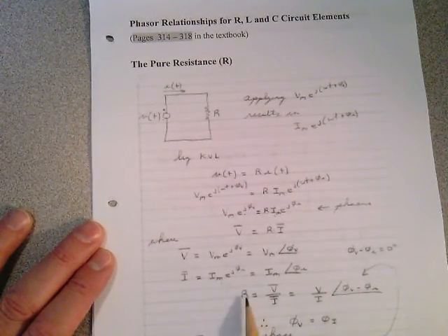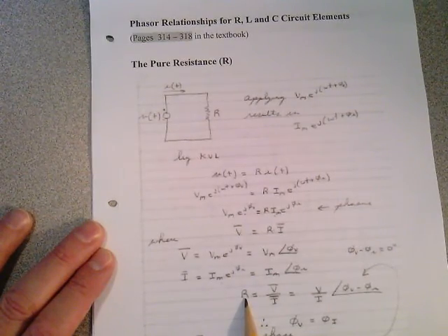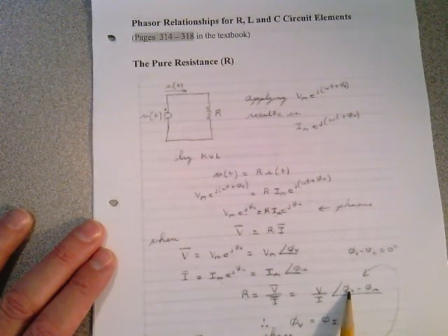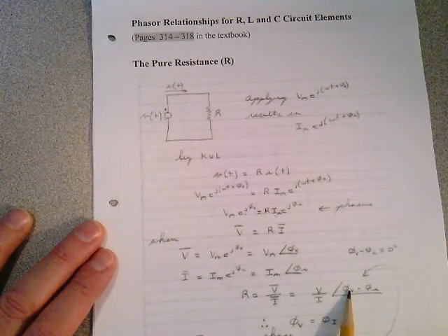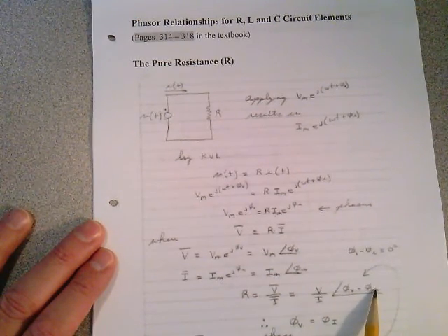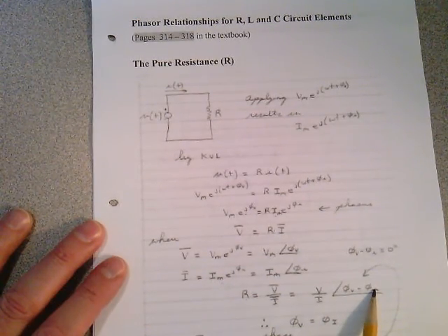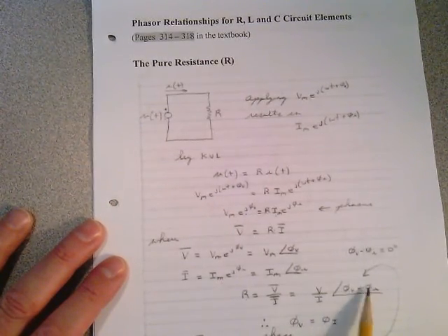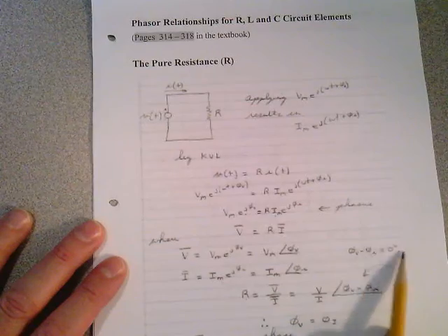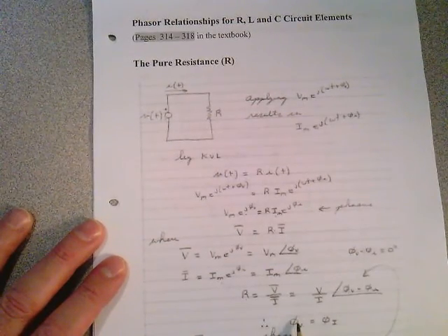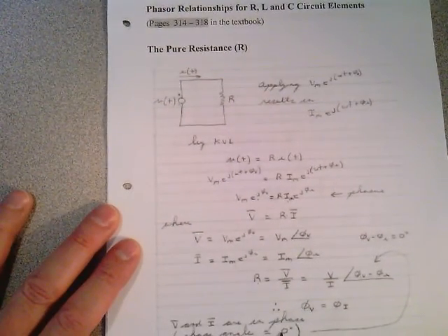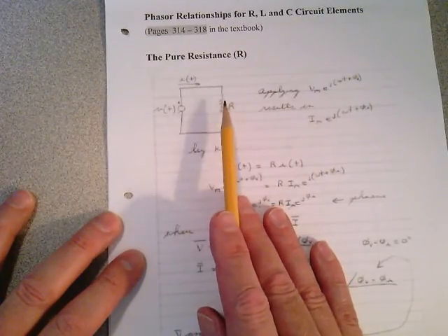That's why, when you're forming the resistance here, we already talked about this too, it's equal to the phase angle associated with the numerator minus the phase angle associated with the denominator. These two angles are the same angles. They'll always be the same angles, so the phase angle is 0. The voltage and the current will always be in phase when it's a purely resistive load.